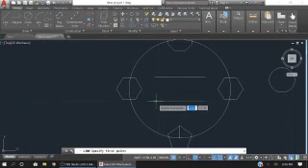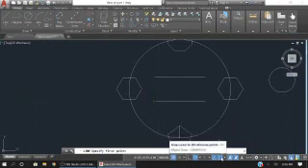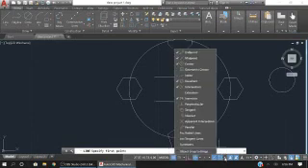How can I get this green box if you guys are not getting it? Over here it says snap cursor to the reference point. Right next to it there's a down arrow key. If you click here, choose the end point. It will be set for you. And you need quadrant for the circle, and you need to enable the center to get the center point so you can move your things.